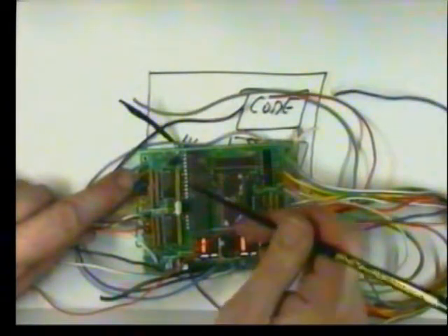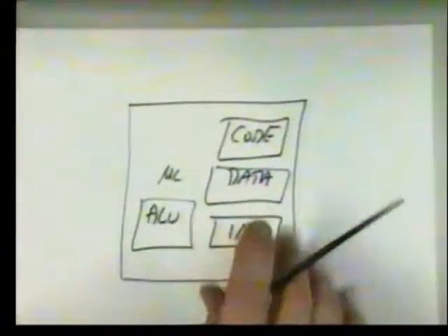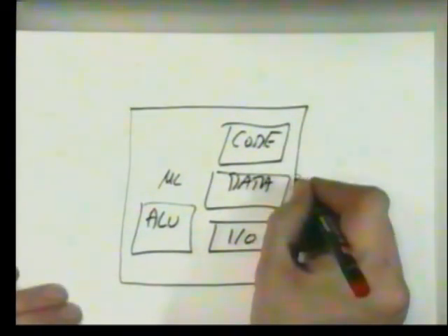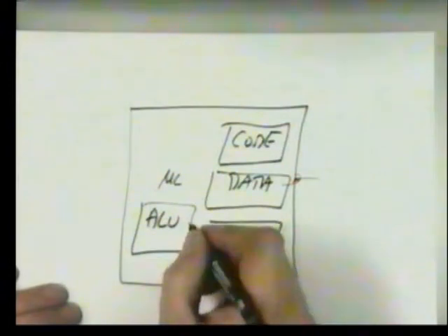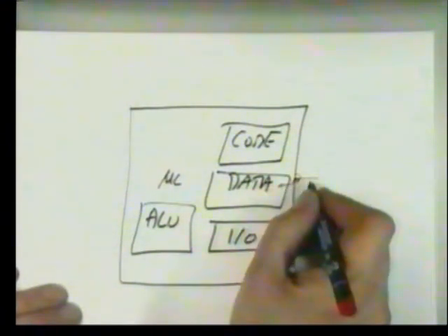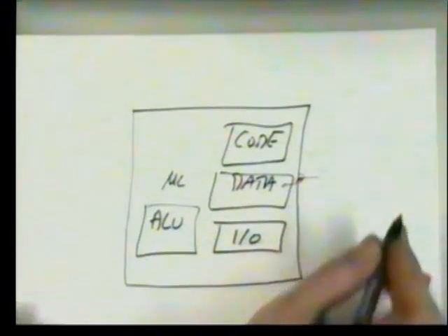These pins go straight into the memory map in the data space of the processor, so if our program, which is stored in the code, has a pointer that points to that memory mapped I/O, we can read the state of an output signal directly. Reading a level is very easy, because all our program has to do is point to that pin: if that memory location is high, it's on, if it's low, it's off. That's easy. What about timing?